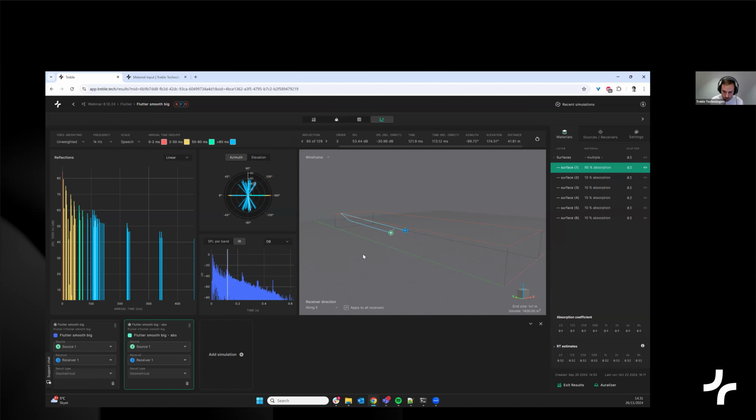And this is coming due to the fact that with added absorption in the ceiling we killed the reflections in that plane. So when they are bouncing from the ceiling and floor, they die very quickly, the sound field, but we still have this 2D sound field that you can see here that is bouncing between the long edges of the model. So go here and then here, and you can see where they're coming from. So this is sound bouncing back and forth.